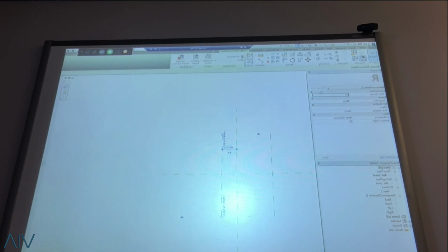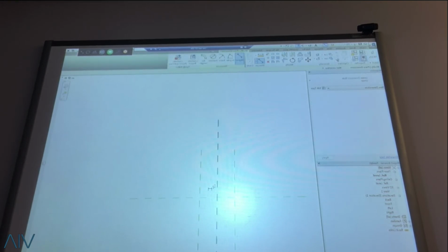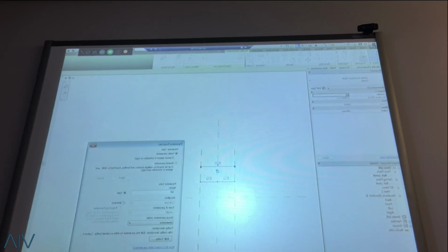On the opposite side, I also put in 400 as well. Now, if you want this to stretch an equal distance, I would usually pick this center line and go to the two outer edges and say equal. What happens is that right now you can say, okay, that one is 800. And here, I'm just going to say this is the width.